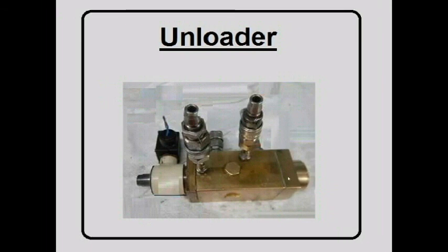Unloader. This prevents the compressor from starting on load. There are some methods to unload the compressor cylinder. They are throttling of suction, speed variation, bypass discharge to suction, depression to hold suction valve plates on their seats. The last two methods are most widely used in marine compressors.